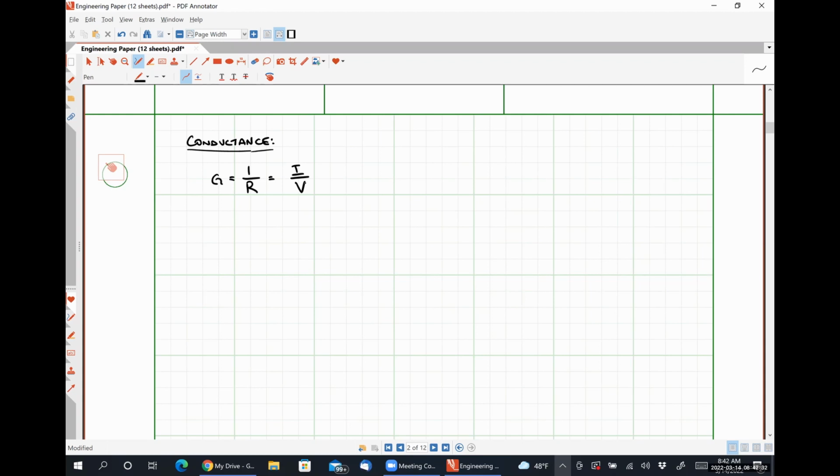So the slope of the graph that you guys got at the end of your mini lab number 1, if you had current on the y-axis and voltage on the x-axis, was actually a measure of the conductance of the component that we were measuring on Friday. Okay.